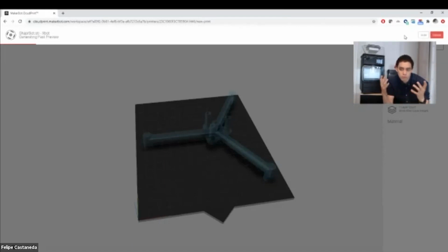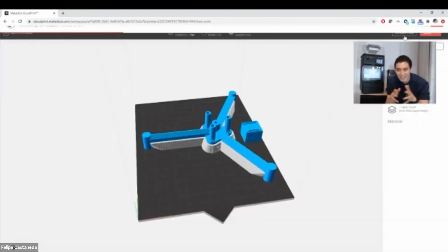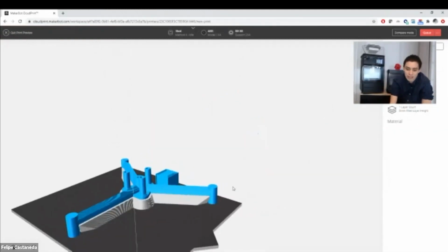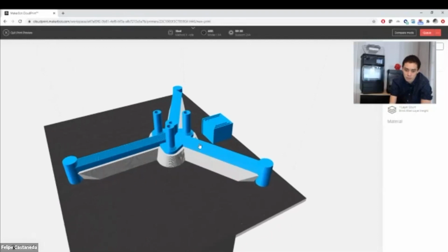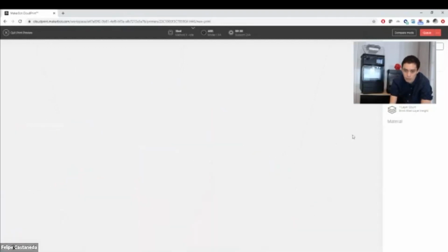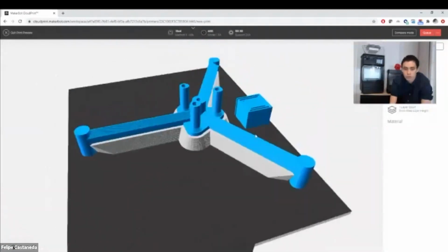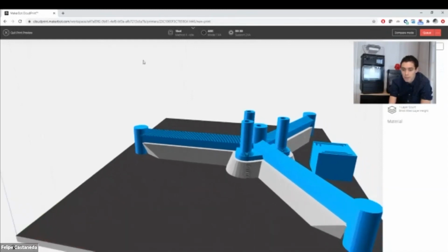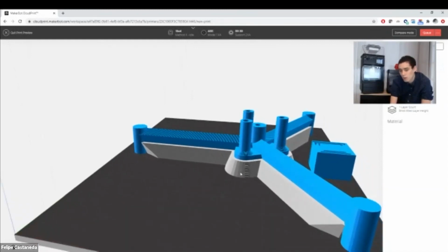And in turn, you can just go ahead and keep working on other projects if you wanted to for those, I don't know, like 30 seconds that it'll take for the rendering and the slicing process to be done. And as you can see here, now my part has turned blue and it's showing me these gray areas, which are the supports that are going to be generated by the printer as it prints, right? As we know, any components of the part that are not self-supported will need something to land onto as they are printed. So that's where we're using supports.